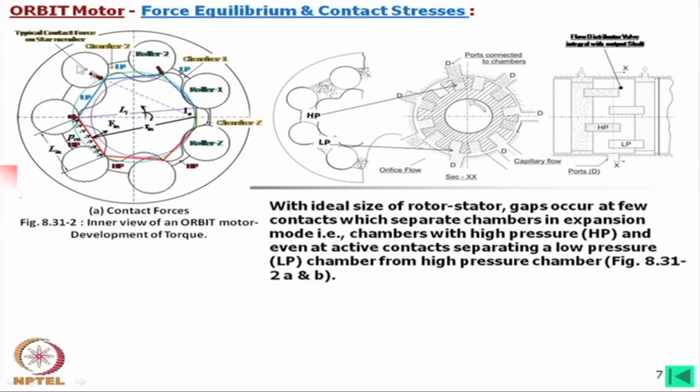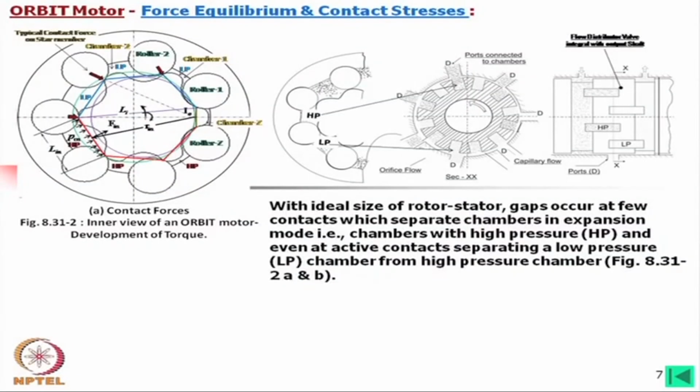Now, also if you look into the support and their direction of force, to find out the direction of force, what we can do, we can join the instantaneous center of rotation to the center of the roller or center of the nodes of the envelope. So, we are getting the direction of the force, direction of the support. But if you look into the direction of the support, these are not parallel or not perpendicular to the beam which we have considered. This is at an angle. So, the problem to find out the loads is not an easy task. We have to consider all the directions.